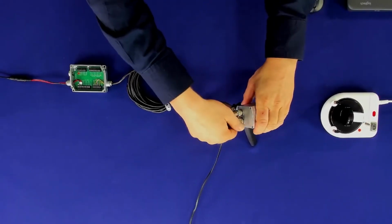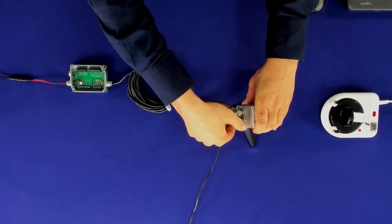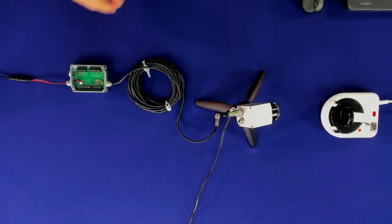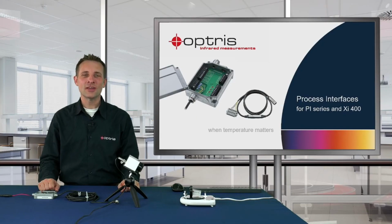I'm going to disconnect the cable from the camera now, and you can see immediately, when I disconnect, that the failsafe LED turns off. So this is a sign that you now have an interruption and you can forward the signal to your system. As we have seen before, you can use the process interface for a bidirectional communication to set values and to get temperature information and alarm states.